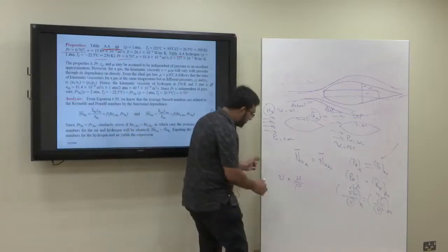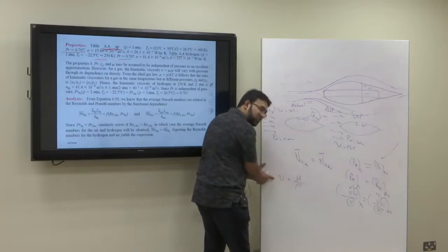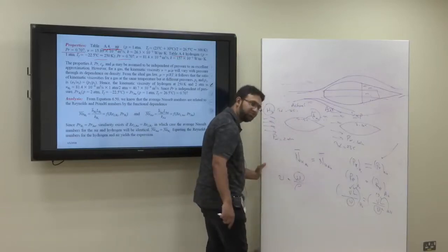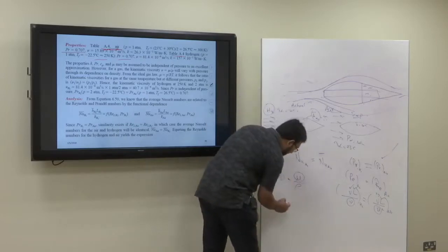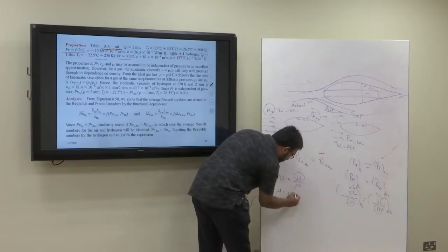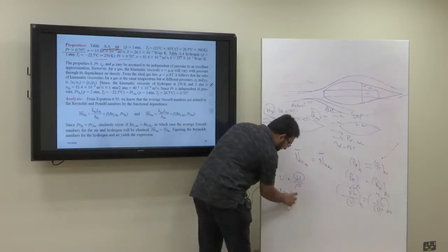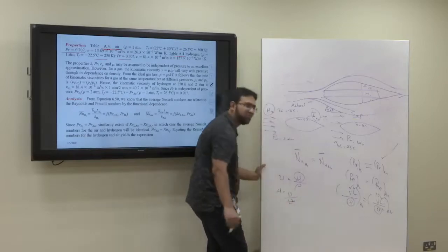Now you know that nu equals mu upon rho, and since density will change with pressure, nu will change with pressure, but mu does not change with pressure. It's only a function of temperature. So basically we can write that mu equals nu into rho, or rho can be written as specific volume, but it's the same symbol, so let me put a dash here for specific volume.